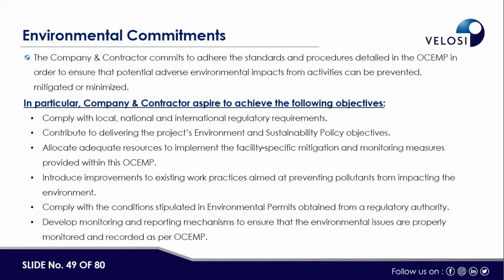Next question. Are EMPs required only for significant impacts or for all EIAs? No, it does not relate to the EIAs basically, and it is not required only for the significant ones. See, for EMP there are two scenarios. Either it can be required by the regulatory authorities, so if the project has a significant impact, the authorities can ask for the development of the environmental management plan even after the approval of the EIA. In the second scenario, it may not be required by any regulatory authority, but the project proponent or the company may develop the EMP to add value to that particular project. In that case, both significant and insignificant impacts have to be covered in the EMP.